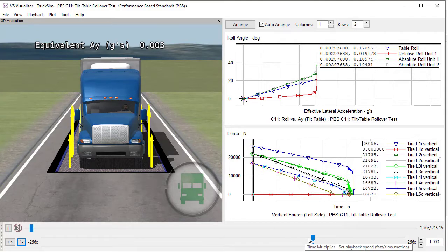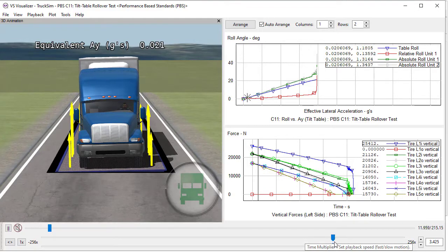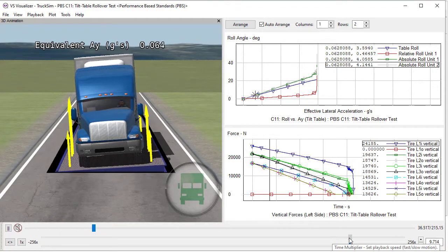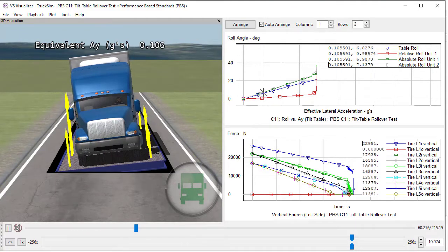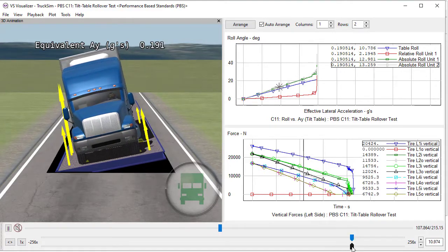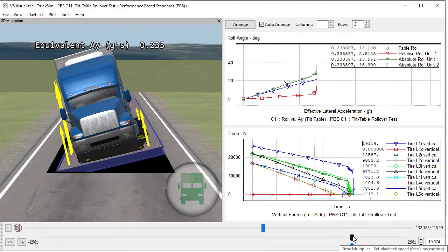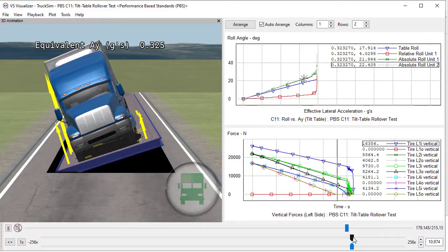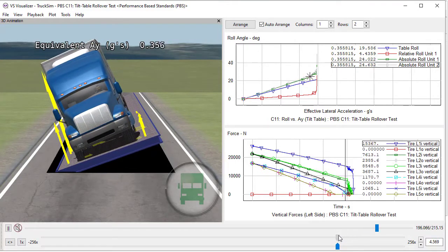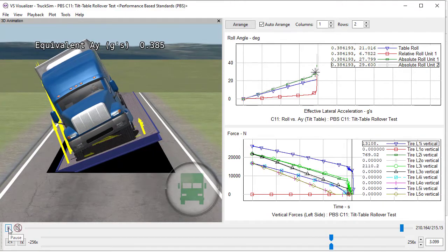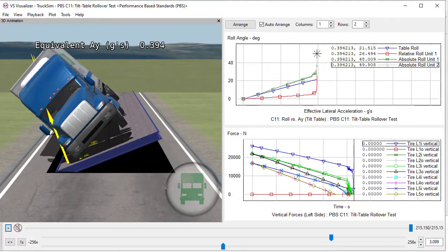Well, doing this with actual cornering tests, where you're going in a circle and you keep going faster until you increase the lateral acceleration, doesn't work very well if you have free differentials, because as soon as you lift off a rear wheel, it starts spinning and all the power from the drivetrain goes into that spinning wheel. So instead we use a tilt table like you're seeing in the animation here. You increase the tilt quasi-statically until the limit is reached. The lateral acceleration is calculated as a function of the tilt angle, and we're speeding this up to show you how we get the limit behavior.